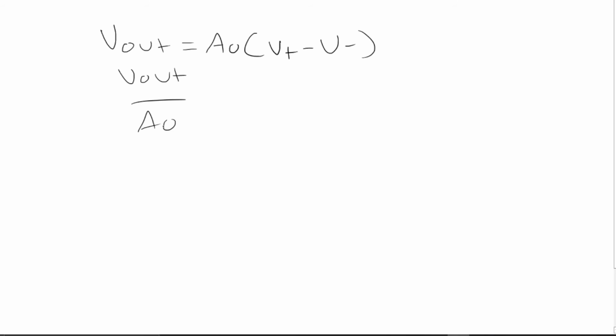What's really interesting is that we can even simplify our op-amp circuits with negative feedback, and this is how rule 4 came about. If we treat this op-amp as an ideal device, we could rearrange our equation. Because we are treating this as an ideal device, this side will equal 0, because ideally we want the gain to be infinite.